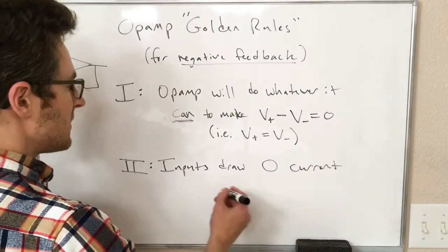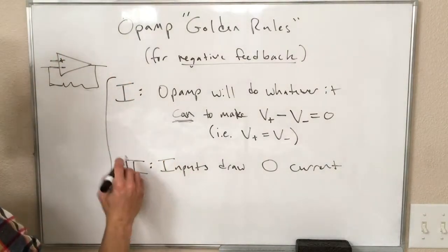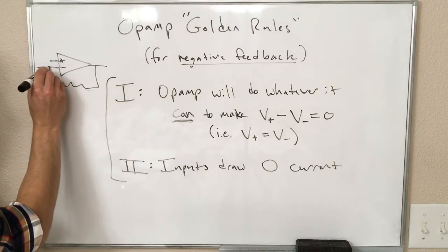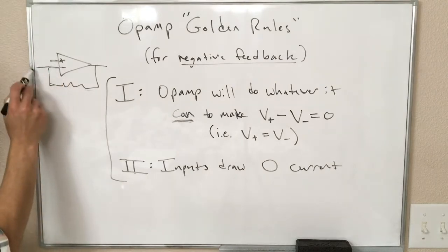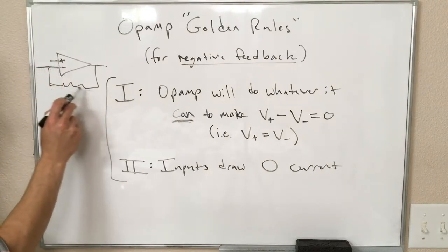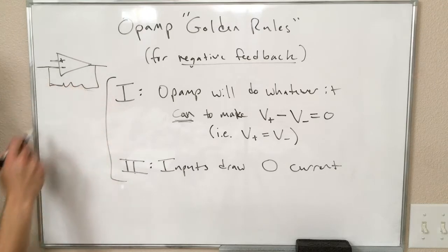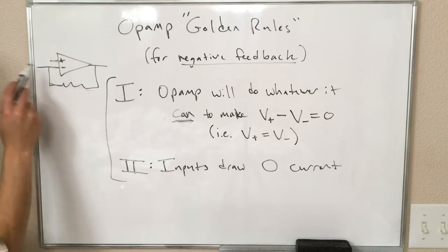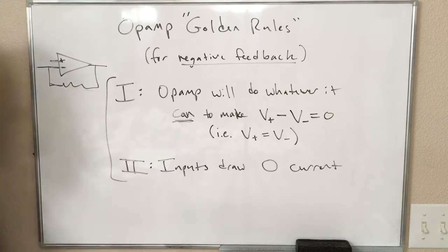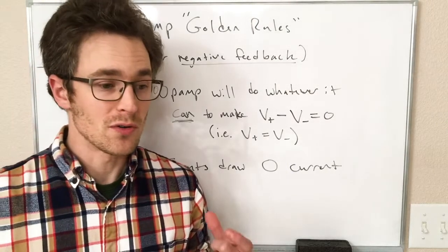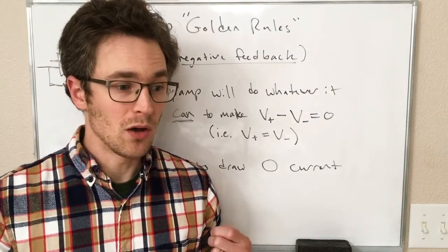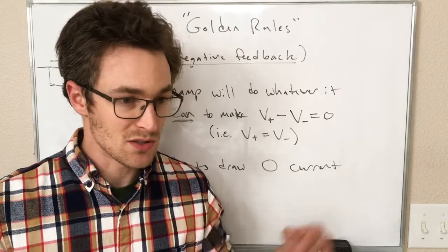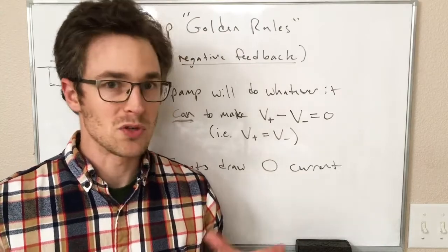So what this means practically is if we have things connected to our inverting input and then things going past it, it's often really easy to look at things in terms of voltage dividers, because remember, voltage dividers only work for components in series, not for things that aren't in series, because there's current that can leak out between the two objects.